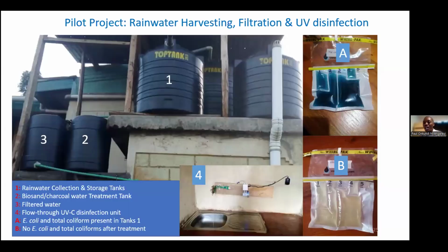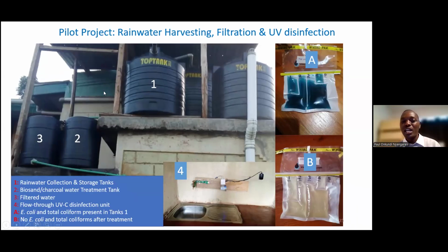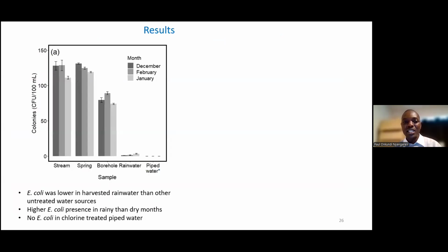Before I started the project which we did, I went home to do a pilot project, and this was just for rainwater. I designed a system, as you can see, collecting the rainwater with tanks on the roofs, and I had a very small UV system, which we got from a company in the USA. The flow rate of this system was 2 liters per minute. I only tested this system at home, because I wanted to see how it would perform. The results I got were like this.